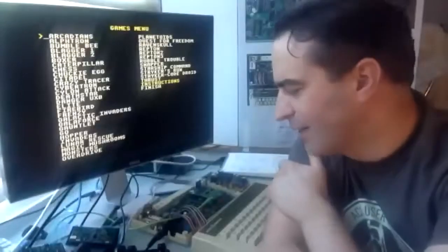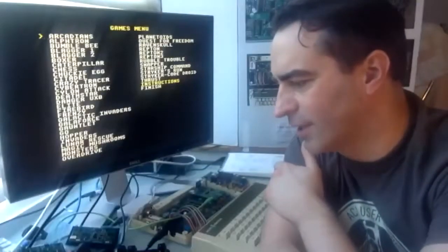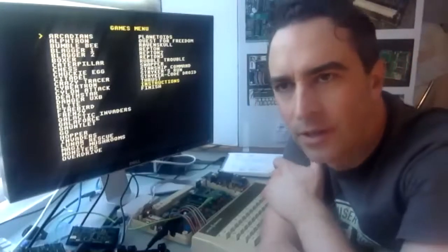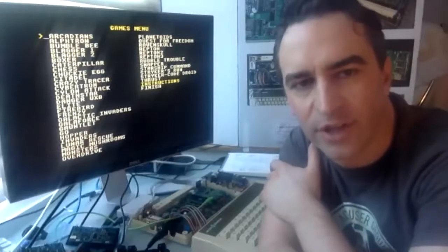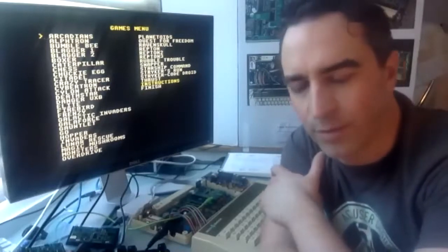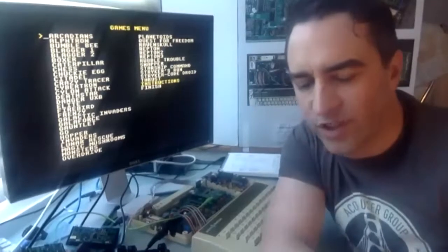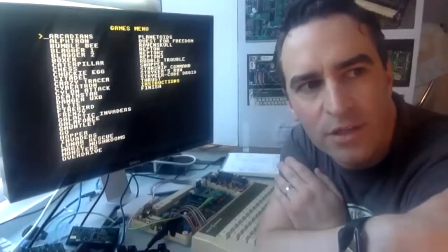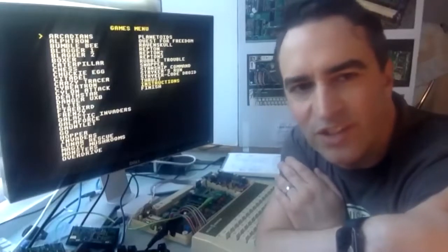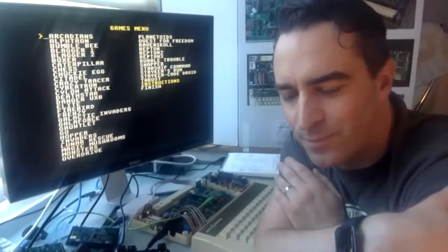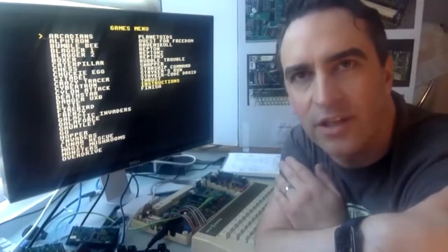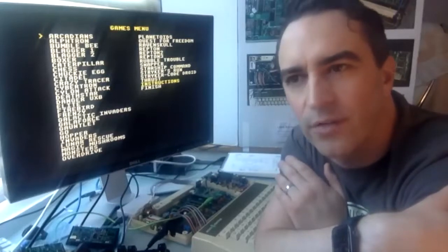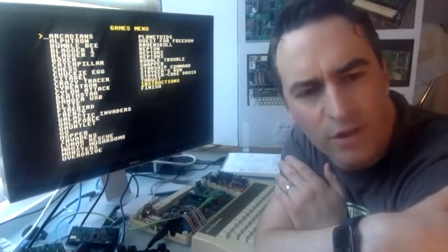I haven't. There seems to be an endless supply of different kinds of buffers, and I poke around every now and then and see what's showing up. But I tend to stick with the ones that I've used and have found to be reliable. And pretty much, after I got burned by using LVTs, I've just been designing with LVC and HCT recently. I'm a little wary of the CB3T ones.